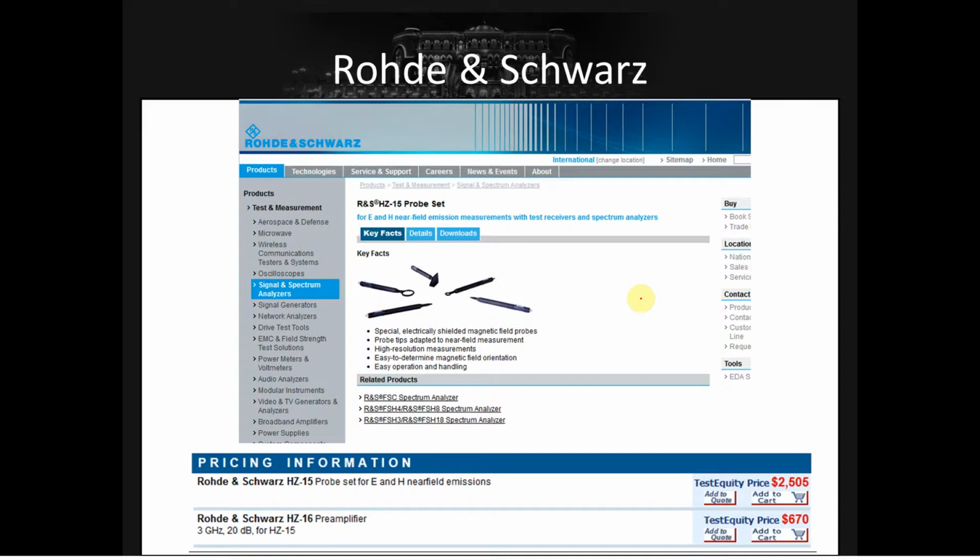Are people really going to do this and then somehow use it without getting noticed? And the answer to that is that the basic idea of monitoring the data line switching is what we're doing. The basic idea isn't to use the power, despite the name. And we can pick up those switchings in a whole bunch of other ways. It doesn't have to be just a resistive shunt.